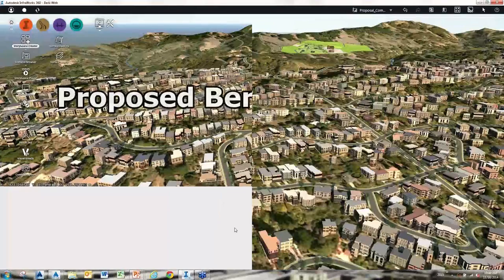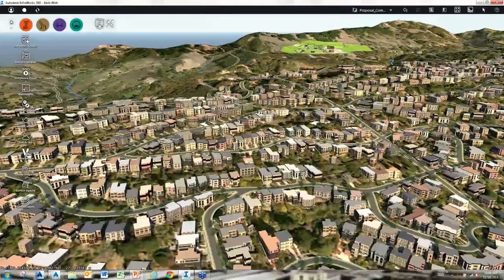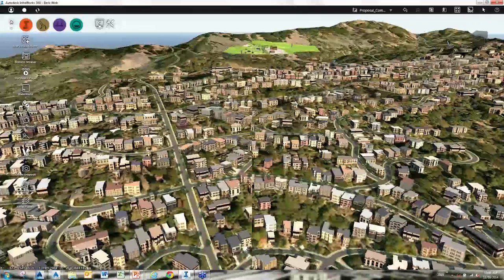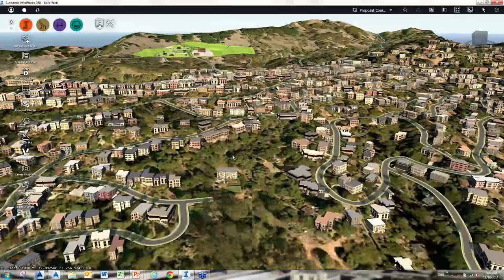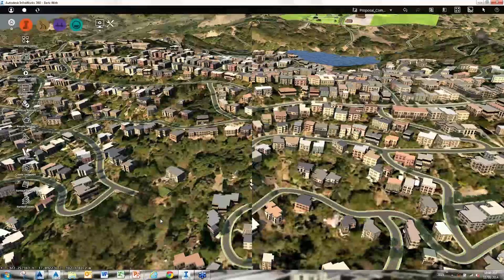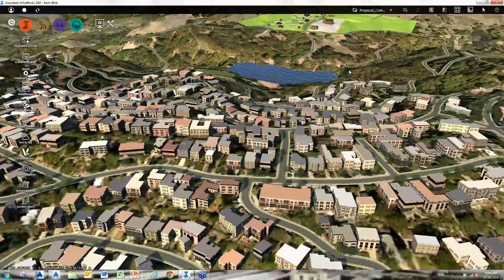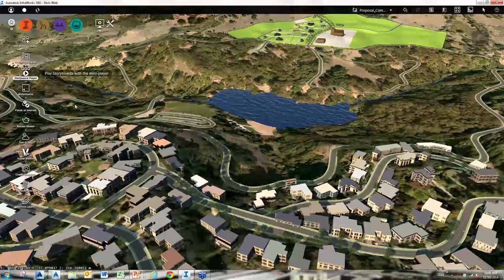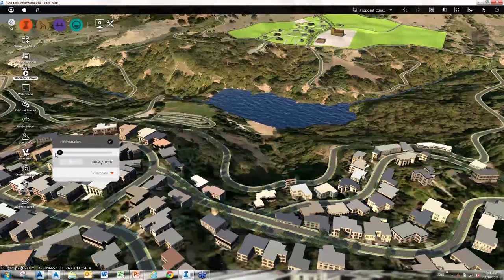Once you have all that in there, it's pretty simple to just zoom to a location and then drag that snapshot right onto the storyboard. And then zoom to another location and add that snapshot to the storyboard as well. And as you continue to do this, the software will seam those together and transition from site to site and location to location, generating an animation for you. And when you get done, that animation can be played live or can be exported out again to a video file format, an AVI or an MPEG or something, that again you can post to a website, you can email to somebody.